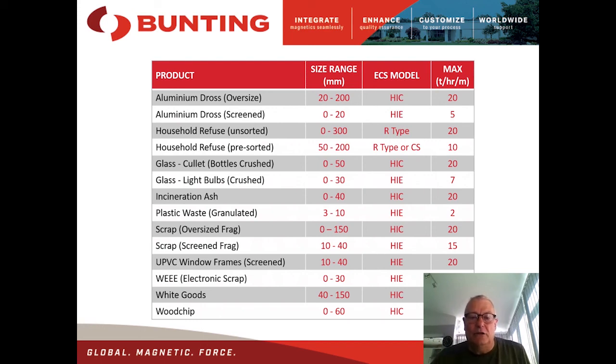And a different type of unit is specified. You see, for the finer particle size ranges, we're specifying the eccentric unit. For the larger particle size range, in 440 millimetres, we're specifying the concentric unit. So there's not a best type of eddy current separator. There is the best type of eddy current separator for the client's specific application. And what we would do in our test centre is test them on different units and come up with a flow sheet that would optimise the separation for the client and also optimise the cost benefit that they will get from the process.